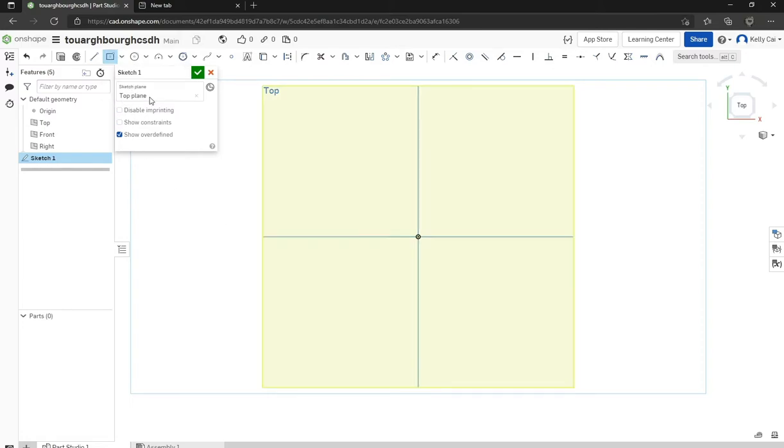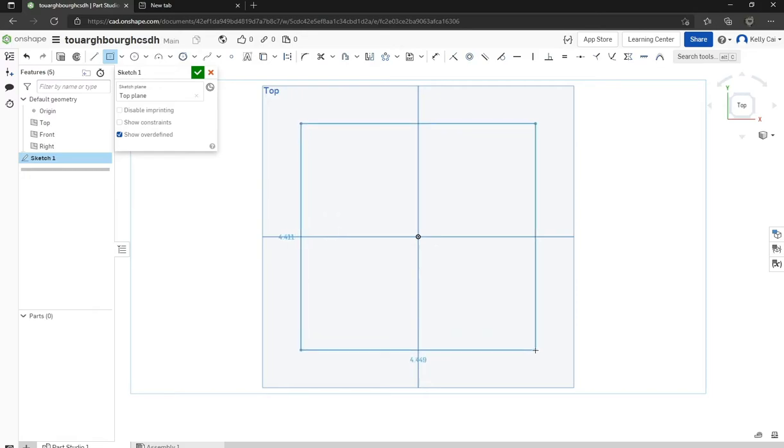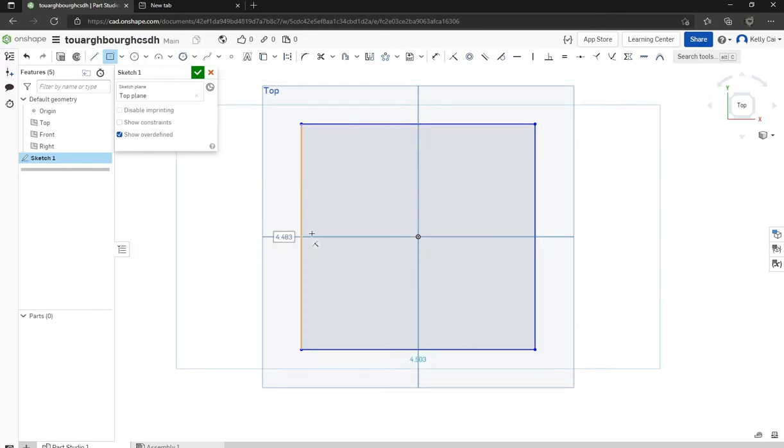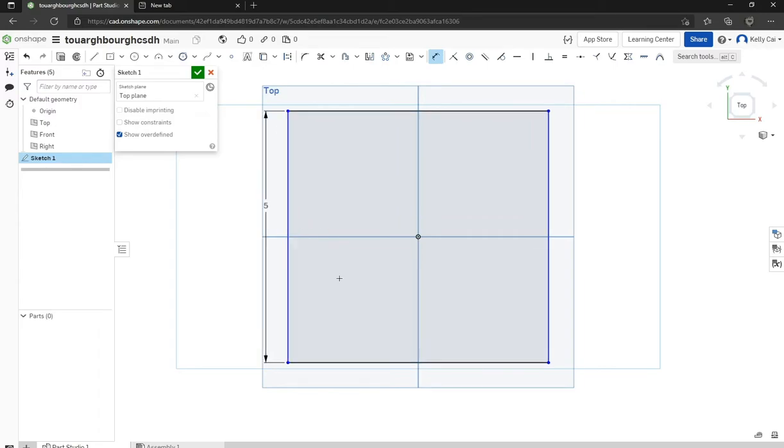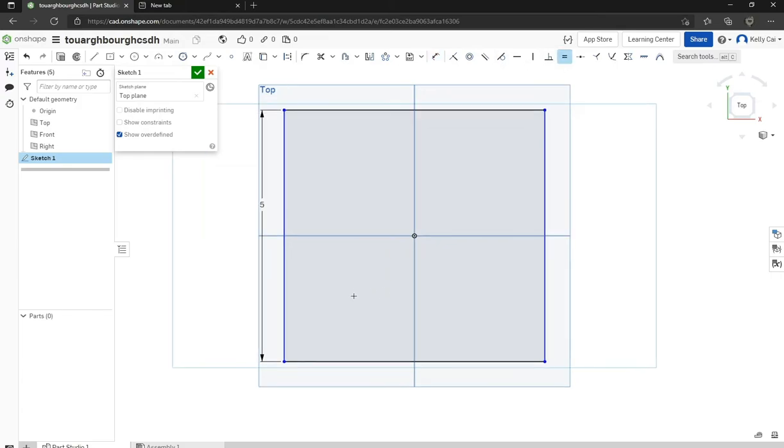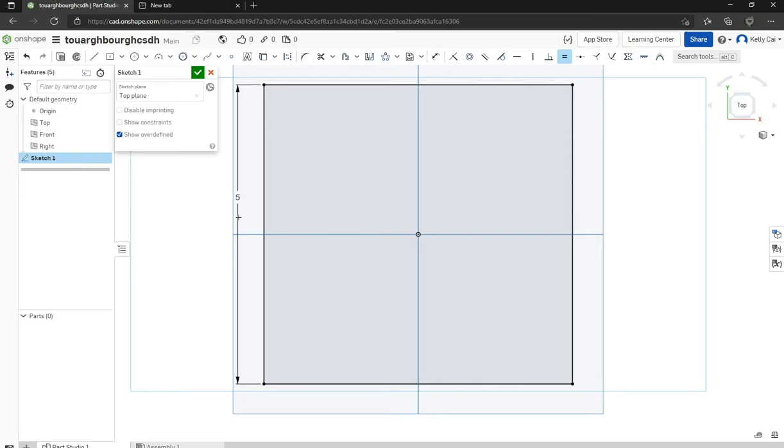So first of all, let's use the center point rectangle. Let's do this. Dimension, which shortcut D, and then you can set the values equal. So that way, that's like a really fast, really simple way. You can just set these equal since you already defined these lengths. Then if you just set them equal to the lines that aren't defined, then they'll basically always become the ones that are already defined.